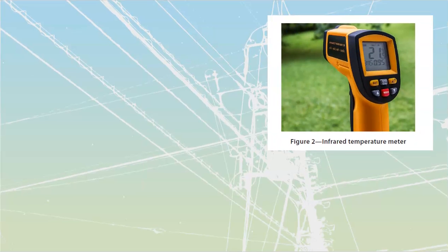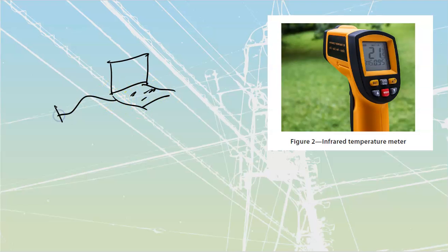Oscilloscopes are very expensive. They're also getting a lot more accessible. If you work off of a laptop at any point, I work off of a laptop, you should have just a little black box oscilloscope. Most of the cost inside of an oscilloscope is going to be the software that processes and displays the graphics, as well as the screen and all the push buttons and knobs. What we have in a lot of cases, and they're becoming really popular out there, is one that's going to be USB connected to your computer.